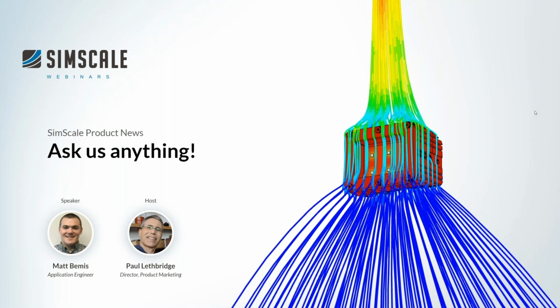But removing those pins on the chips, removing those ID numbers and letters is time consuming. So in this case, you can leave it all on there. It's fine if your geometry has interferences or tolerance issues, no problem at all. And we just can run the analyses and go with it.